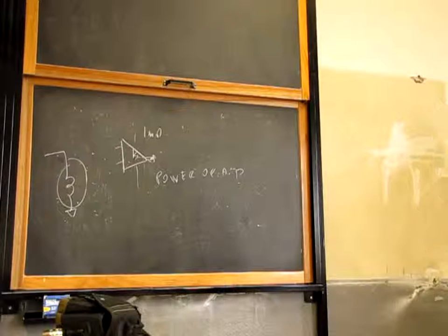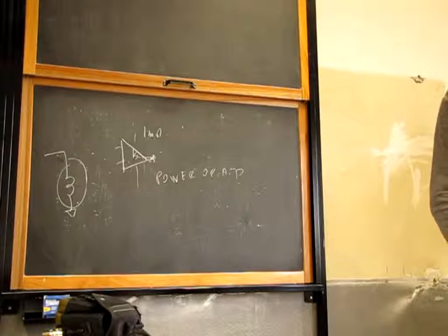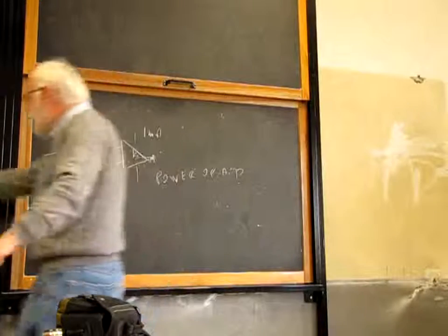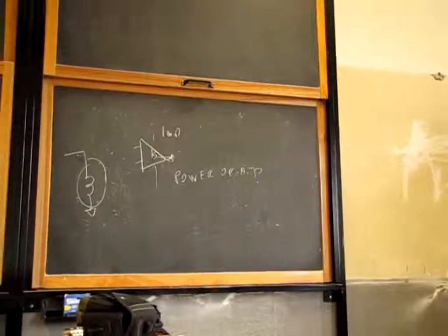One part of this class will be about stresses for components. When you design an inductor, I don't need just the inductance value. I need the inductance value, the current flowing through it, the peak current, the RMS current, etc. We will see stress analysis. So, nice try, but not working.